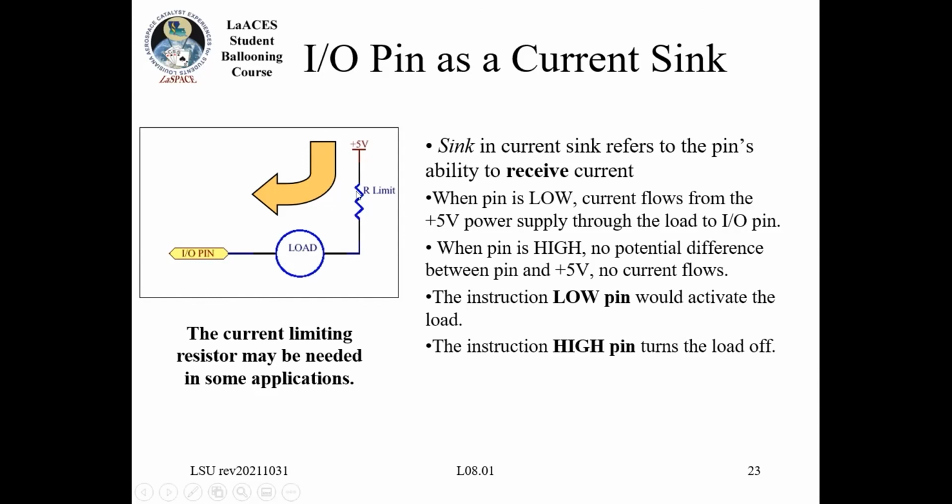And in particular, depending on what is on these loads, you probably want to know what the default behavior of your IO pins is. Are they going to default low or default high? Because there will be a brief time, when you first power on your microcontroller, before your software actually gets up and running. So you want to set this up in such a way that your load doesn't turn on before you really want it to be on, right?